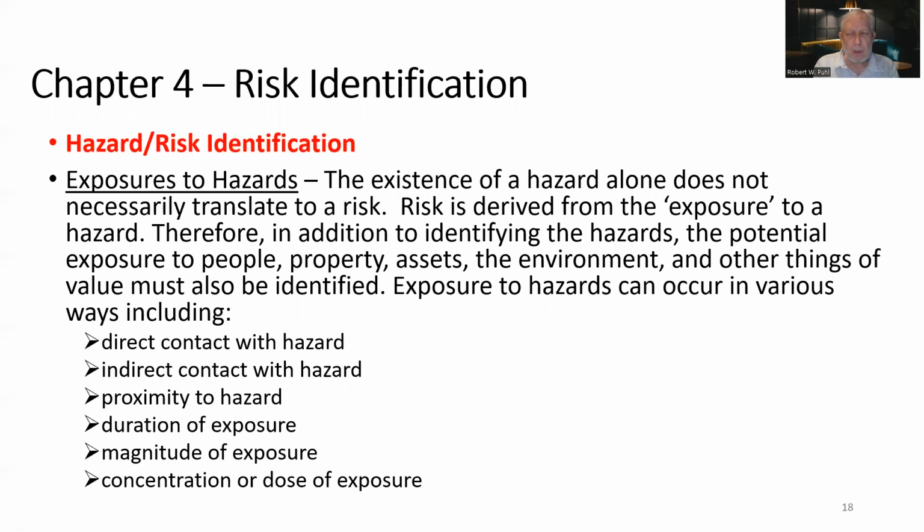We had OK Foods an OSHA inspector, and there was a pulley and a belt which was high up, and I don't know what was running it, a fan or something inside a piece of equipment, and it wasn't guarded, but it was 10 feet off the ground, and there was no walkway, working surface below it, so there was no exposure to it. So did we get written up for it? No, there was no exposure. Had that been 3 feet off the floor, well, it would have been guarded because I've seen it, but it would have certainly been a hazard and a violation.